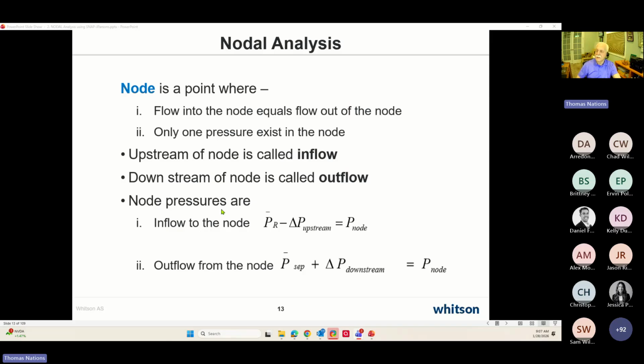It's the tubing IDs where the fluids are going to flow to the surface. It's the deviation of the wellbore. It's the roughness of the pipe. It's the wellhead size. And is there a choke body? Is the choke pinched back? How many elbows are in the flow line? And what size is the flow line? All those different things, but it's basically two, inflow and outflow.